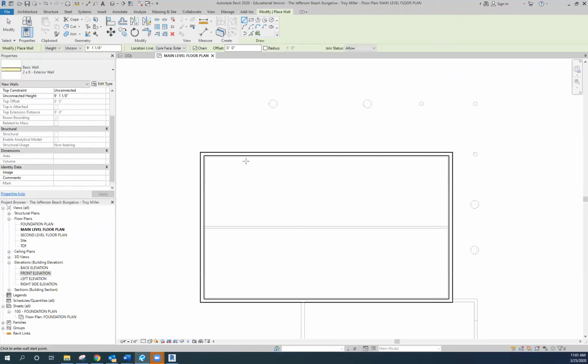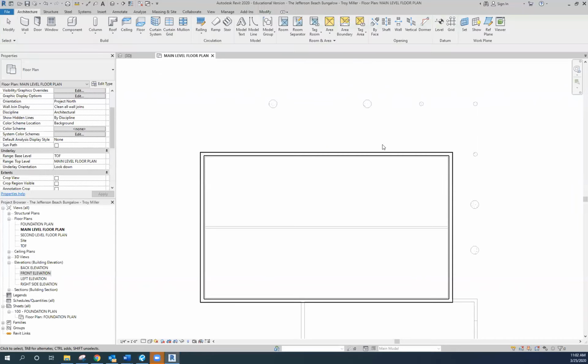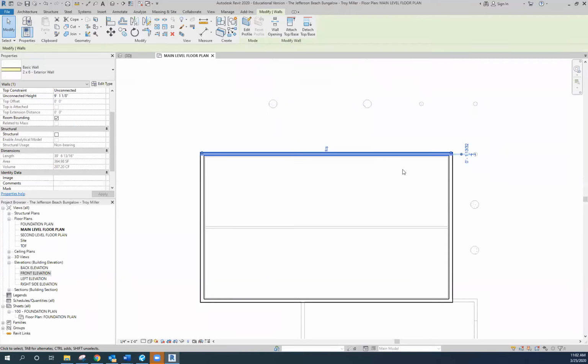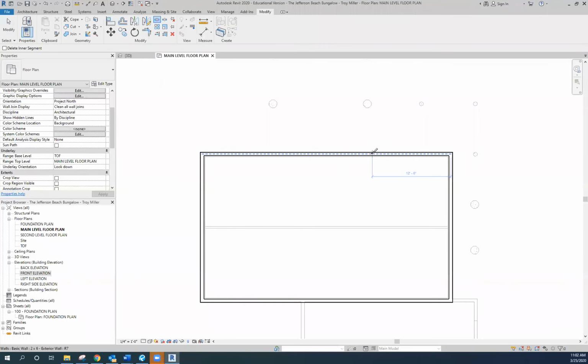So we already developed these exterior walls as a single wall height. What I'm going to do now is hit escape again and get out of that mode completely, and I'm going to select this wall. Once you select an object, it goes into the edit mode inside the ribbon. So if you're looking right here at this icon, this is what we call the split element icon. I'm going to come to my wall and split the wall. At this point, I'm going to come down here to the lower wall and split the wall at that point.